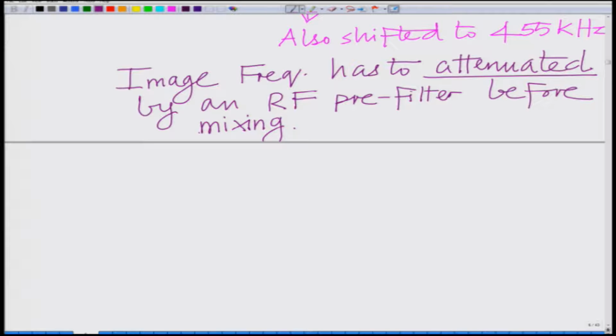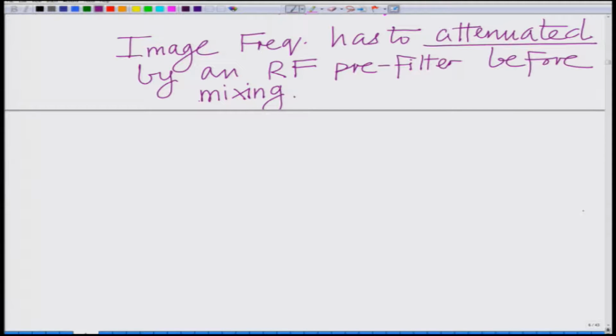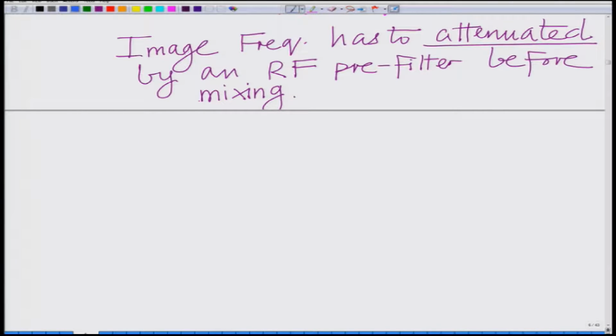Now, realize that in the heterodyning, also note that we have used f1 plus f2 in the heterodyne, that is the frequency of the locally generated oscillator, the frequency of the locally generated carrier wave. Okay. Now, realize that one can also use f1 minus f2 where f2 is the intermediate frequency. So, also note that f1 minus f2 can be employed for mixing.